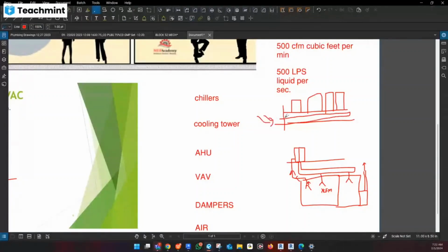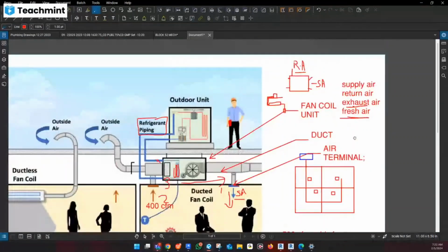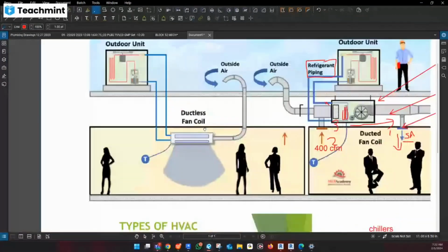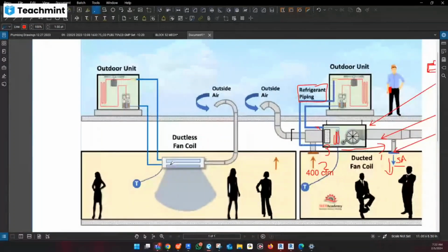They can put one fan over here and install a diffuser, just for the normal air requirement in the corridor. So for the specific case, they can install fresh air also. Even you can see here, the outside air will be required. There is no specific duct system required.